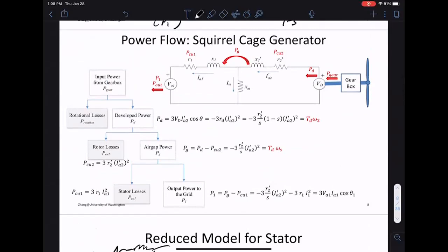But as always, for us engineers, what you want to do is optimize. If you know some negative S generates power, the next question engineers ask is, what S generates the maximum amount of power? What is the most efficient? What is the maximum power I can generate out of this? Because for sure the power depends on the slip.